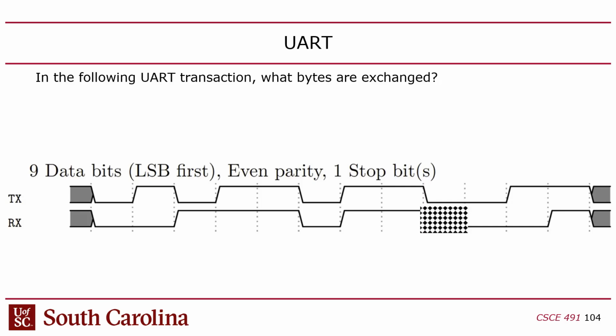Does that make sense? So when you do this, you include the data and the parity together as one glob of data. You count the number of 1 bits, and it should be always even, right? So in this case, I've got 1, 2, 3, 4, 5. I'm only counting 5, but I don't know what this bit is, right? Well, obviously, I know what it is. It should be a 1, because it can't be 0, right? Because if it was 0, it would violate the even parity.